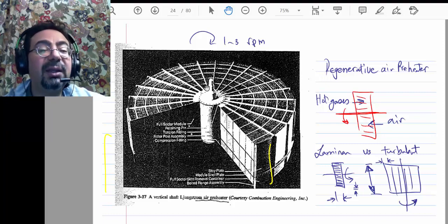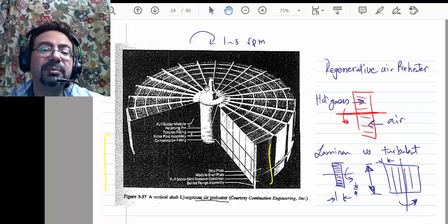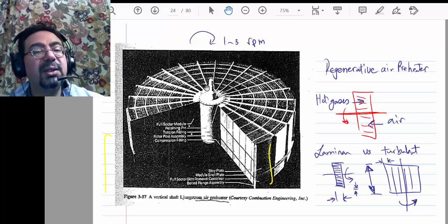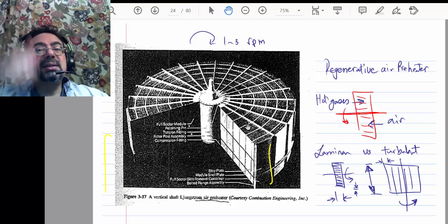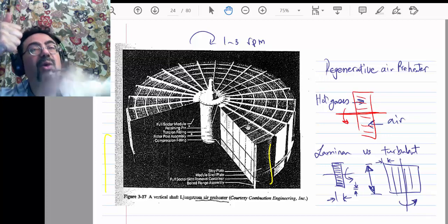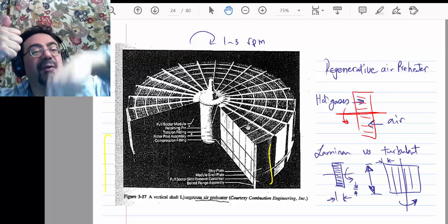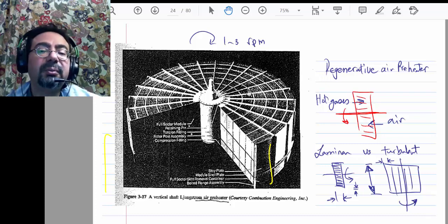Or it could be hot air in the middle of the winter, and why would I throw that very hot air? But you have to, because of the circulation. Otherwise the place will be stuffy and people will not be able to breathe. So you use this wheel between the air you're throwing away and the cold air in the winter, or the hot air in the summer, that's coming in fresh. You make that heat transfer.